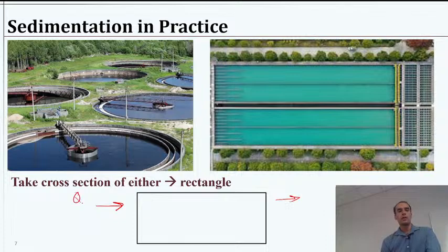If this is our flow rate, we want the particles to reach the bottom, because as soon as they touch the bottom, we consider them removed. Typically, we will be collecting water from the top, or near the top. But as soon as they stick on the bottom, they're going to stick to other particles. They are removed for the purpose of our reactor.